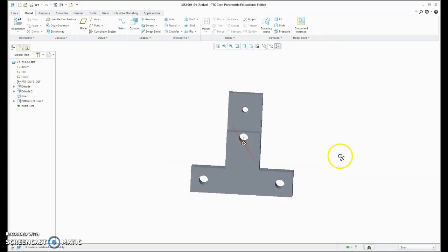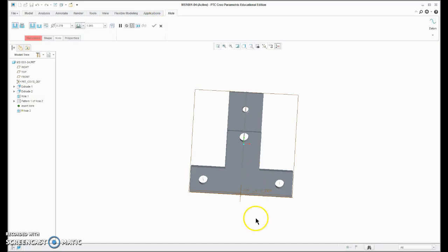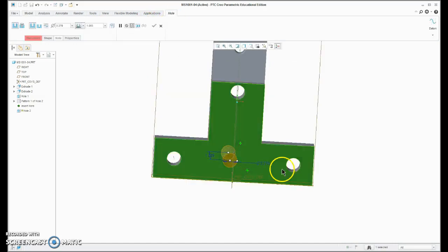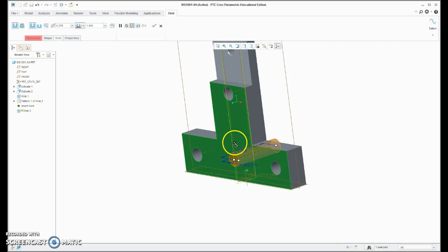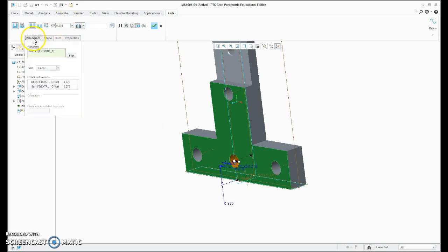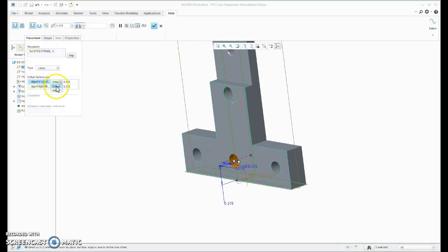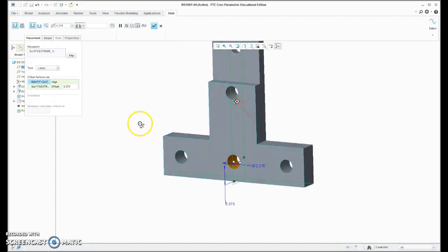Alright, so now the other holes I need is I'm going to put a hole in the middle here. It's lined up with the middle and goes from the bottom. And these are at the same height as the last ones, 0.375. They go through forever, and they're aligned with the middle. And this one is 0.18.